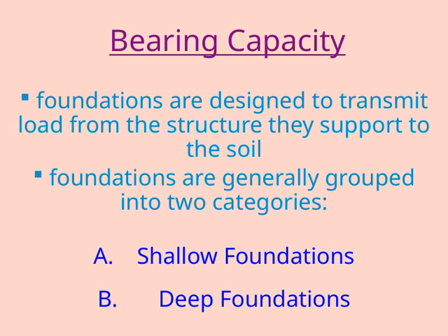The first is shallow foundations. These are used when the soil has good bearing capacity close to the surface, and they typically transfer the load at a relatively shallow depth. The second category is deep foundations. These are necessary when the surface soil isn't strong enough to support the load, so the foundation must reach down to firmer, more stable soil or rock layers.